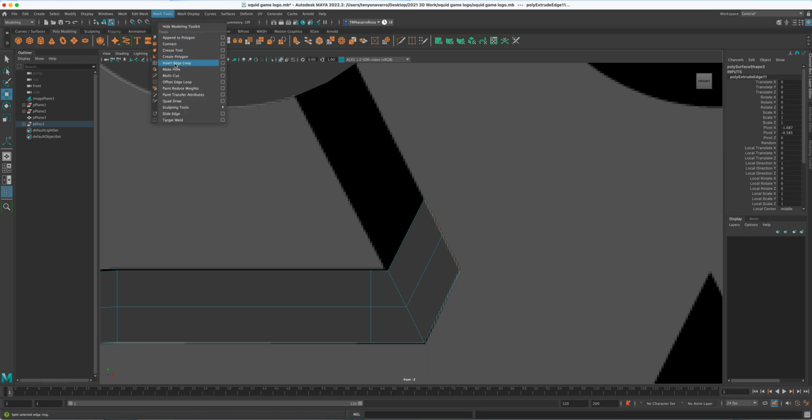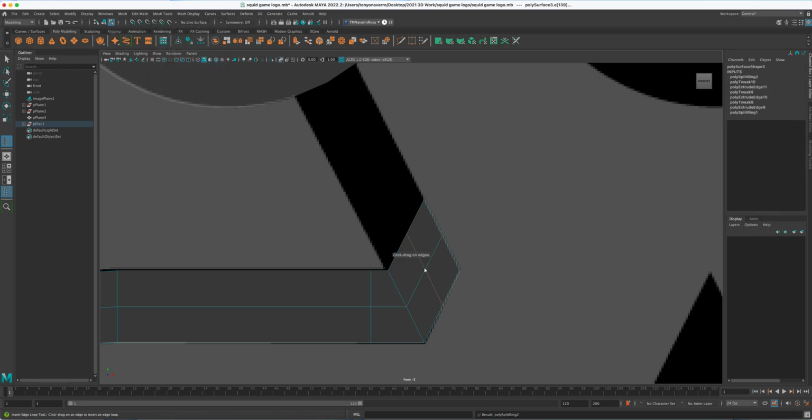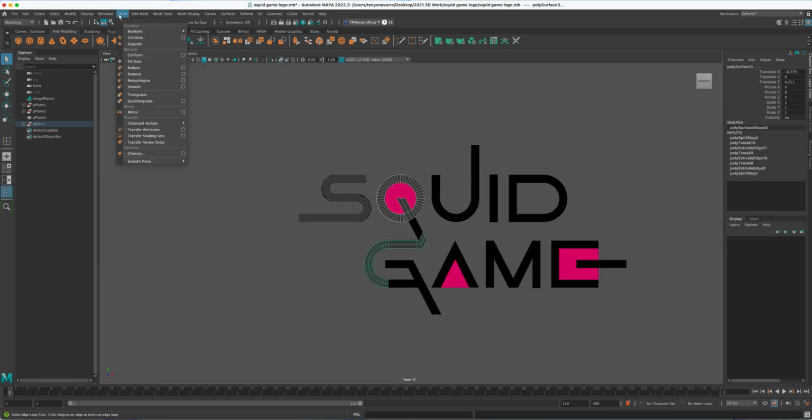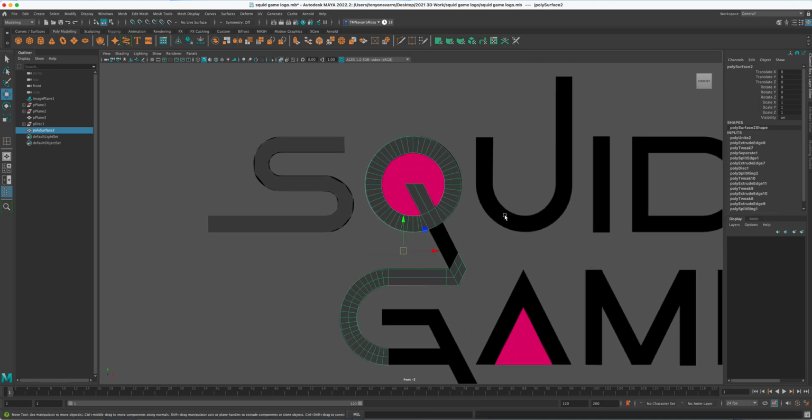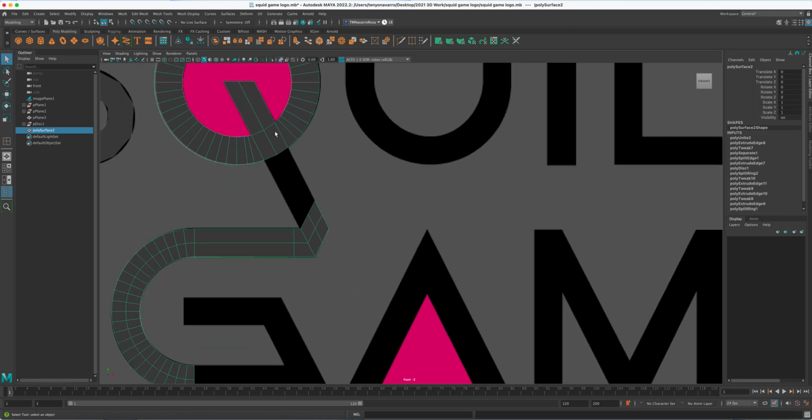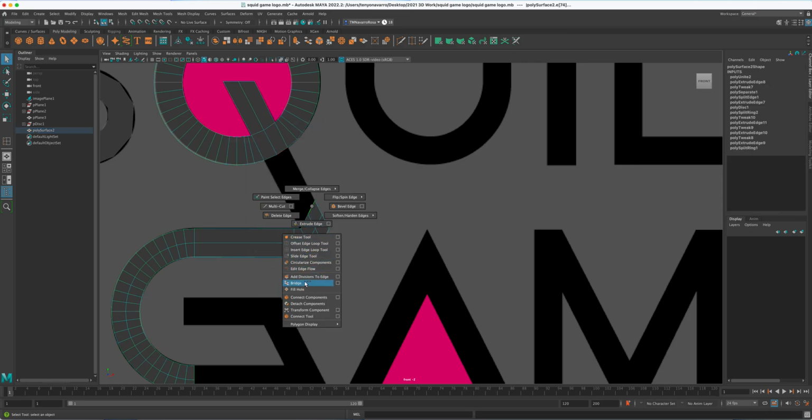Mesh tool, insert an edge loop. It should be right in the middle. That's fine with me. Click object mode. Click, shift click, mesh combine, Command S or Control S to save. We're gonna take edge 1, 2, right click, shift right click, bridge.